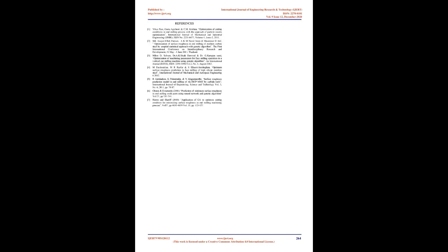For results and discussion: in this paper, we apply GA for the 3 input parameter case in order to compare the results with PSO. GA and PSO are implemented in MATLAB software by applying several conditions and parameter constraints for surface roughness and material removal rate. Population size and maximum generation selected for GA and PSO are 50 and 10,000 respectively. Number of parameters and initial range of parameters are given to GA and PSO. In GA, the mutation function selected is uniform and the mutation rate selected is 0.2. The selection function in GA is roulette and migration is selected as forward.